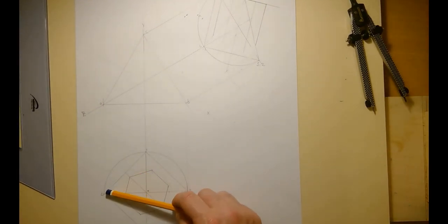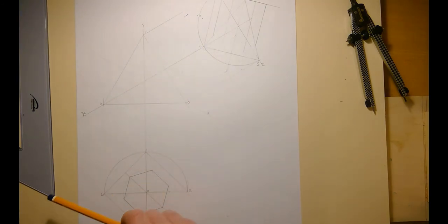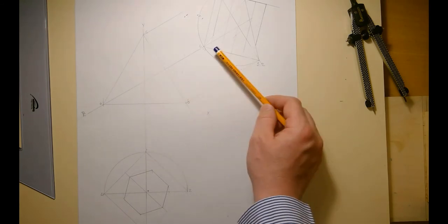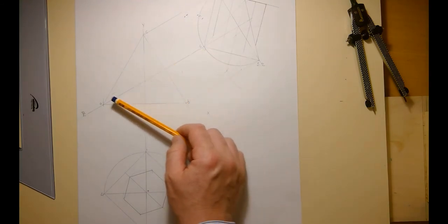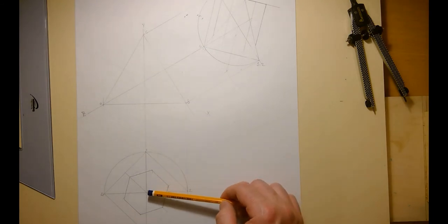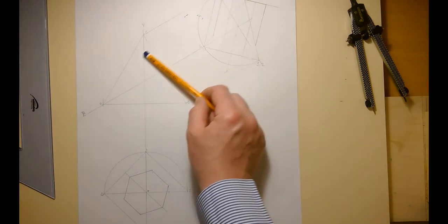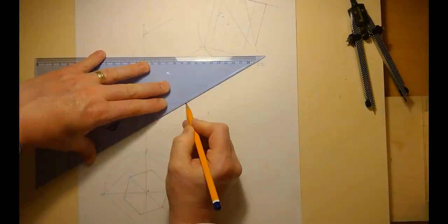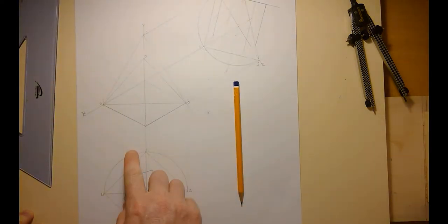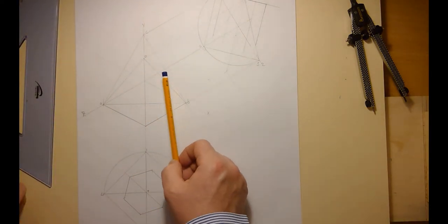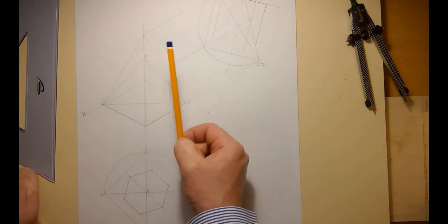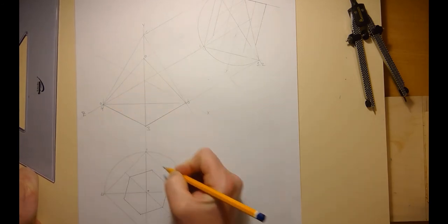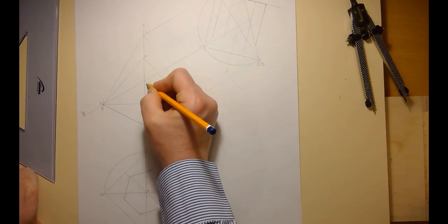So basically I project up from 4, out from 4, and I have my point. Up from 3, out from 3, up from 2, out from 2, up from 1, and out from 1. And that gives me my shape up here. Same for the top point, which I will do as well: up from 0 and out from 0, and that'll give me my points. Okay, so I have my projections carried up there. Most of them are already done for me anyway, and it outlines my pyramid. So this corner here, being the bottom corner, is 3. This is 4. This corner here is 2. And corner 1 there is at the back.